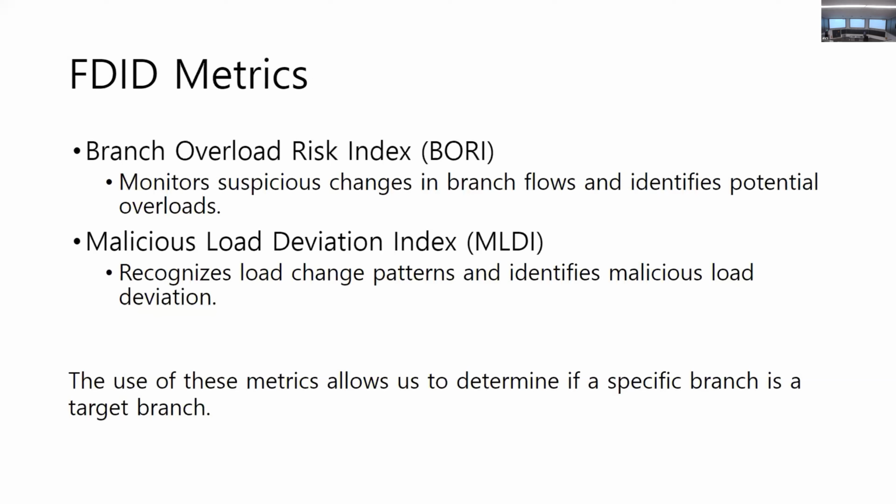BORI stands for Branch Overload Risk Index. This index monitors suspicious change in branch flows and identifies potential overloads. We also have MLDI, which stands for Malicious Load Deviation Index. This index recognizes load change patterns and identifies malicious load deviation. The use of these metrics allows us to determine if a specific branch is a targeted branch of a cyber attack.